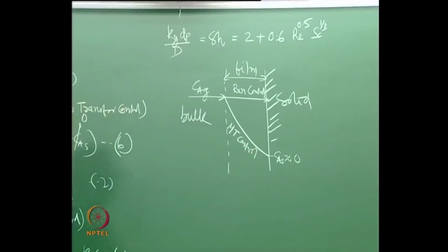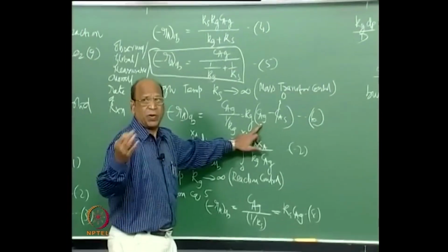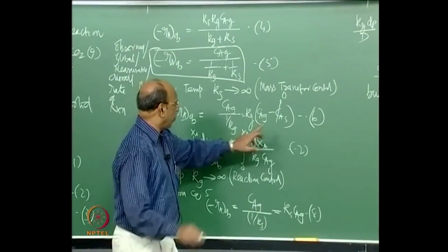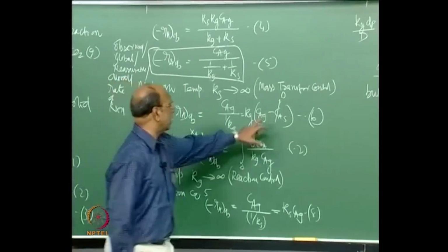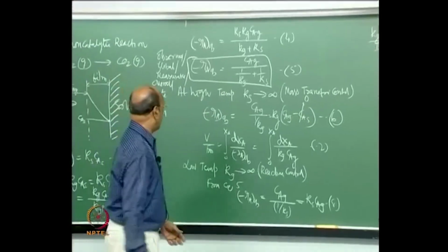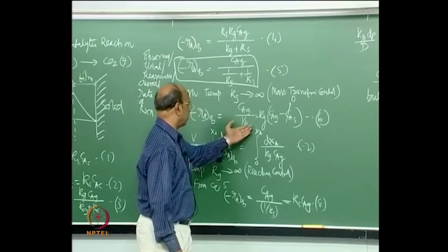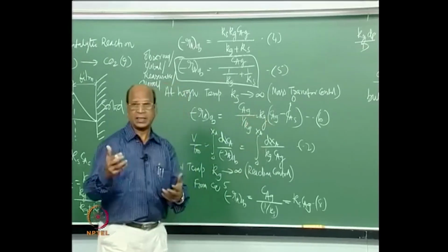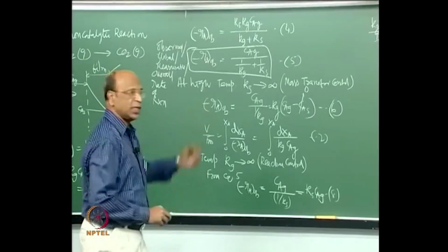Yeah, that is mass transfer control, and this is what I have given here. Always for mass transfer, you will be very comfortable if you write CAG minus CAS, but here CAS equals 0. And for the reactor design expression, I have to use now the mass transfer coefficient. There is no more reaction rate constant. And what are the problems we may face with this?